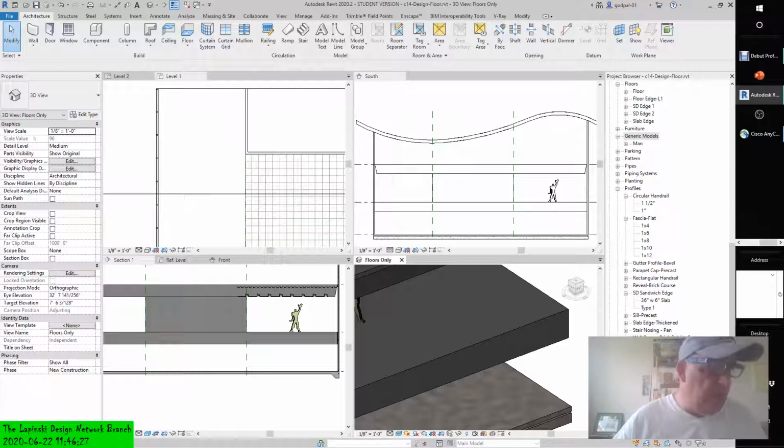When you need to add small areas of thick floor finishes, you may encounter one of two scenarios, with a depressed floor and without. In areas such as bathrooms, a thick-set tile floor may require the structural slab to be depressed in order to accommodate the thickness of the finished material. The main floor object in this figure that I'm about to do is going to be cut with an opening at the inside face of the walls.